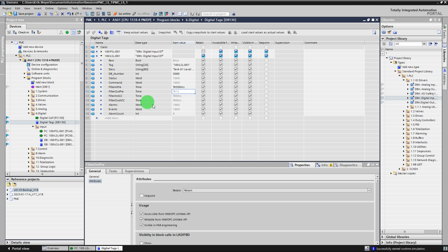Output, this is for the enabling of the alarm. I want it to be a bit delayed because my tank can vary throughout the day and I don't want any nuisance alarms coming through to my scale. So let's say that will be 5 seconds.